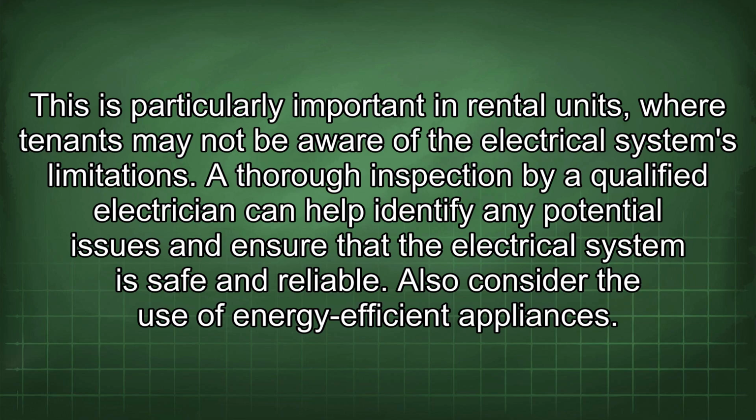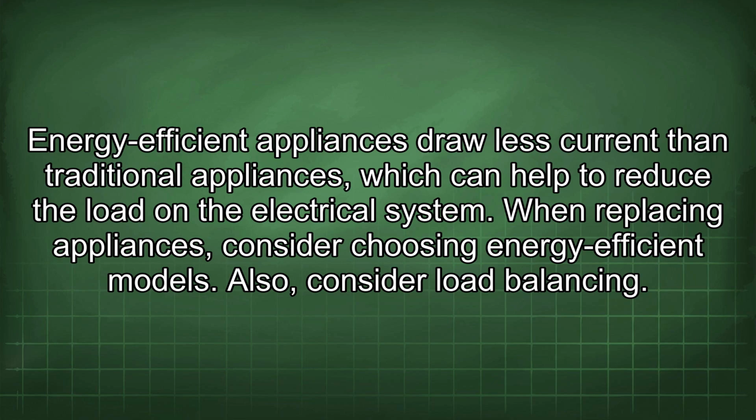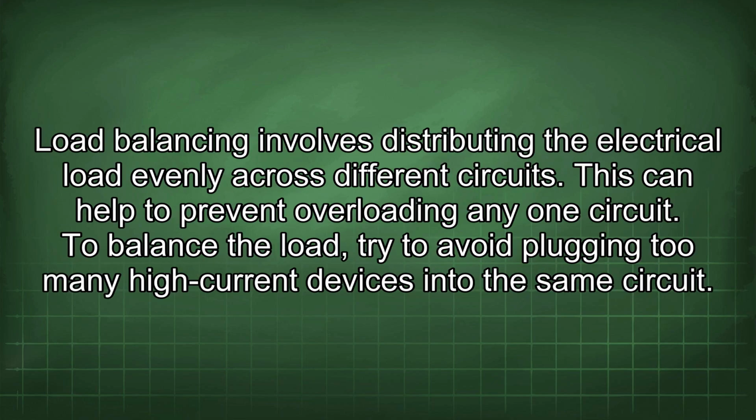Also consider the use of energy-efficient appliances. Energy-efficient appliances draw less current than traditional appliances, which can help to reduce the load on the electrical system. When replacing appliances, consider choosing energy-efficient models. Also, consider load balancing. Load balancing involves distributing the electrical load evenly across different circuits.